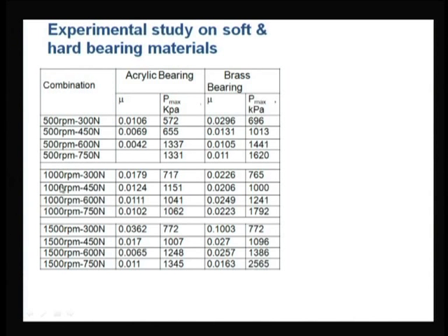Now, if we increase the speed from 500 to 1000, pressure is increasing, which is clear. In hydrodynamic bearing cases, an increase in speed will increase the maximum pressure value and the load carrying capacity will increase. So, in this situation what we are getting is that slowly it is increasing and then subsequently decreasing in the elastic deformation case. Now, this is interesting to note.